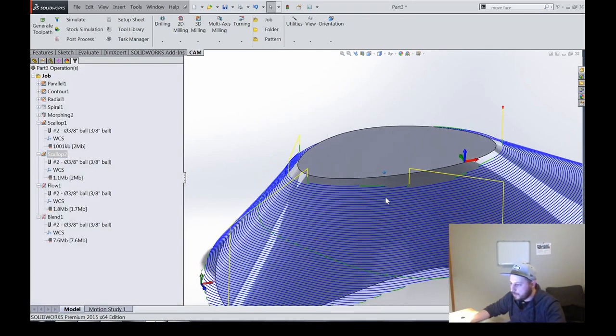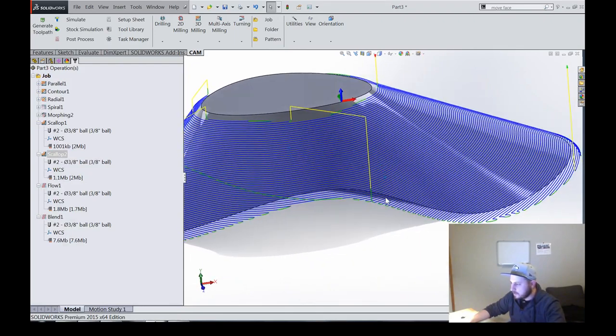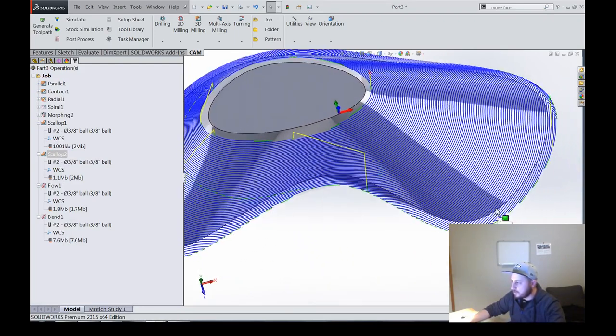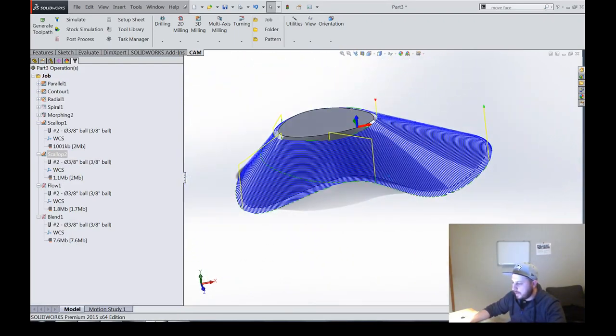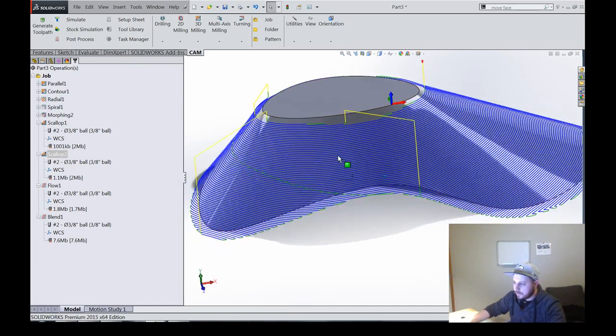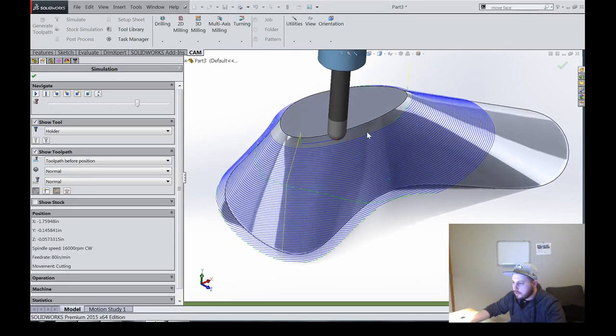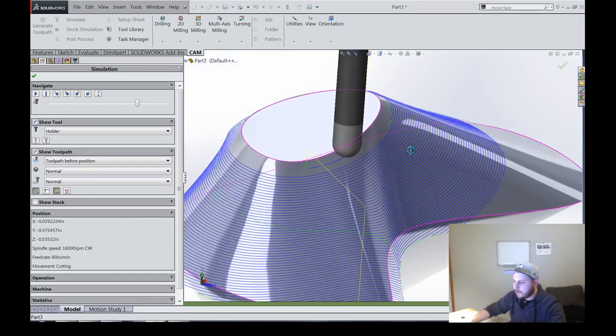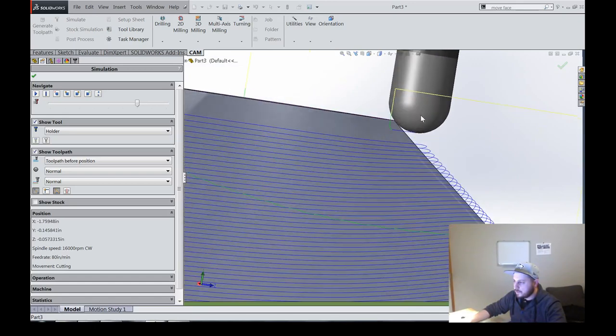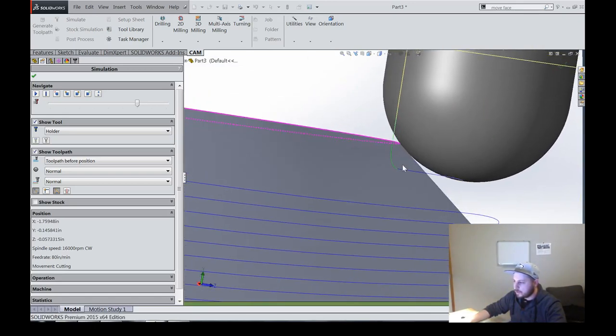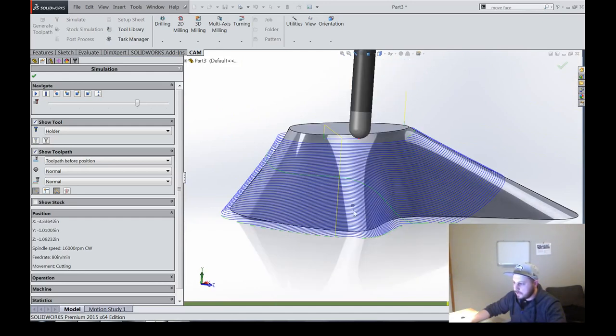And what you wind up with doing that is just an excellent toolpath. There's some collapse going on here. I could offset that outside boundary a little bit more, or smooth it out some more, and get something that's even better. But like I said, it follows geometry perfectly, because I use the check surface on the top, I'm inherently getting a nice perfect stop where this is reaching the tangent point and not going on, within 4/10 or so. So that's pretty good.